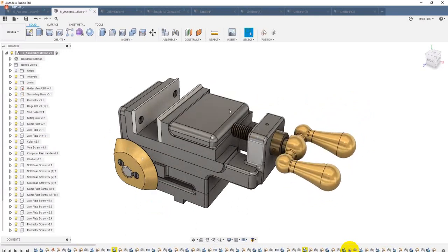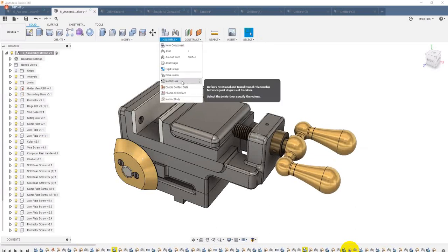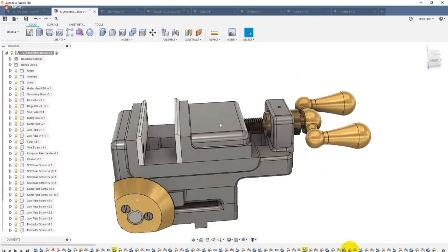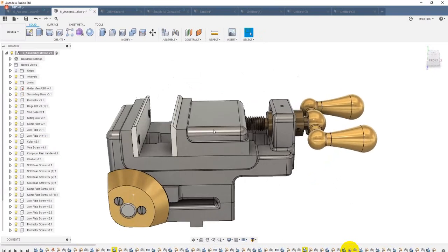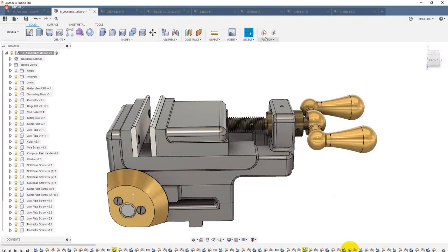But you think it would look better if they interacted with each other. So that is what motion link does, okay? Drive joints allows you to be very specific. I'm going to do the motion link here in just a second. As I'm dragging to the left, I'm just randomly dragging. Who knows how far that's going, okay?